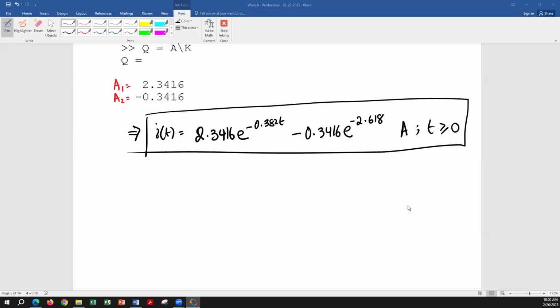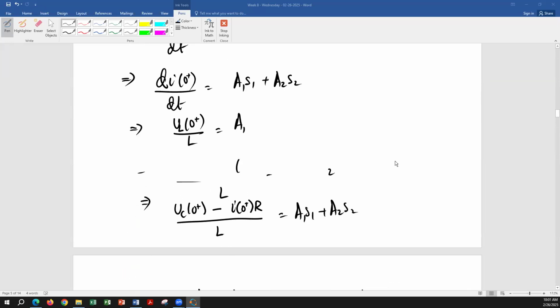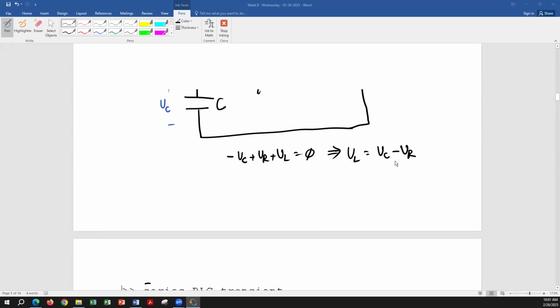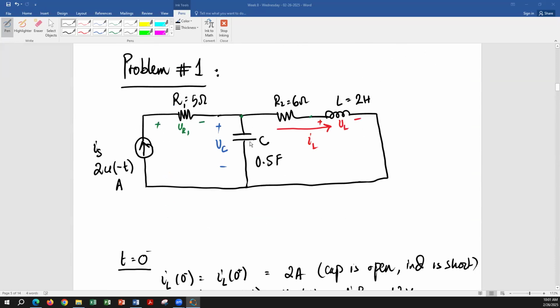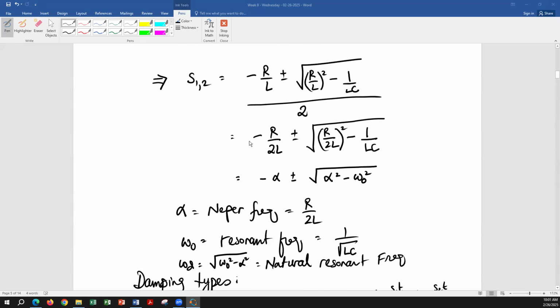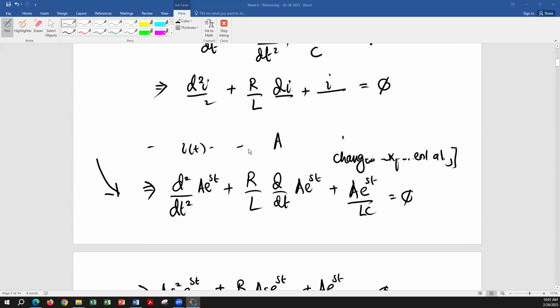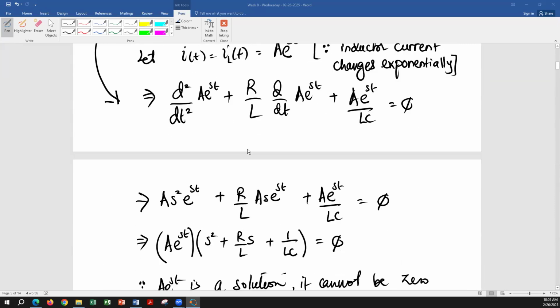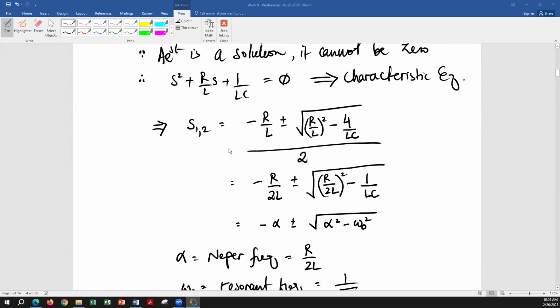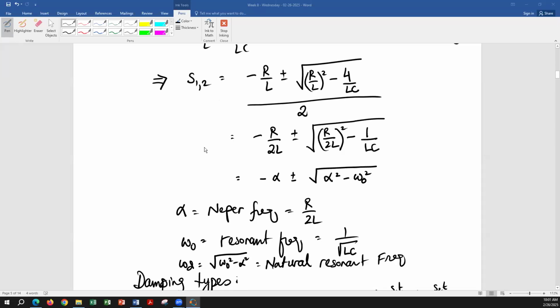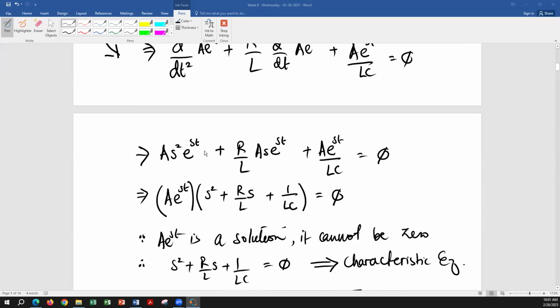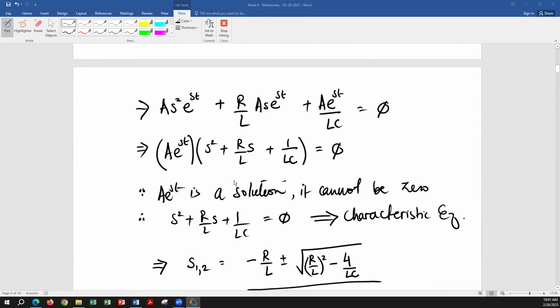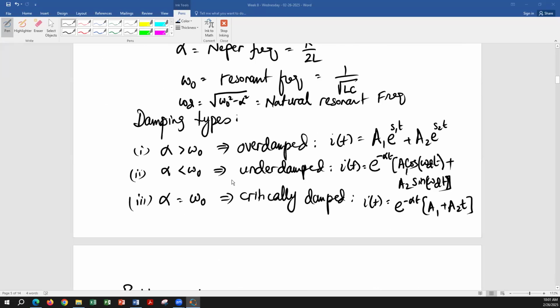How do I go about assigning the voltage and current direction? You can assign. So remember the derivation that we did, right? The derivation that we did is based upon that it's a series circuit and the current is flowing in one direction. And then we wrote down the equation based on that. So you can assign any direction. But if you are going to use the results that we got, then you have to be careful about what is positive and what is negative.